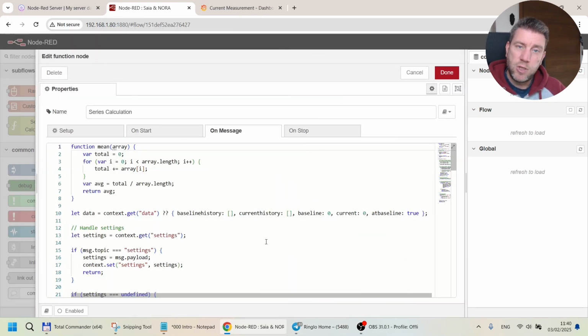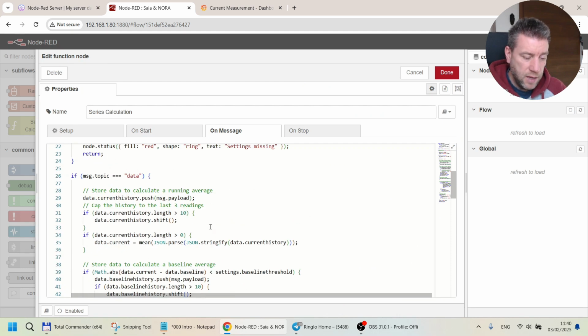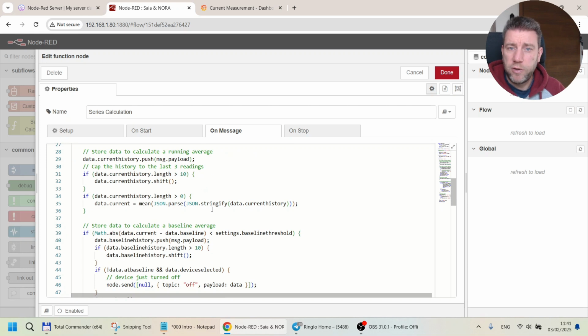So as I said for the dishwasher, because there is a slightly longer period in which it's not really doing anything, I had at least assumed that even when it's not doing anything, it still uses some current, which is, let's say, more than, I don't know, maybe like 100 milliamps, because I haven't really checked the specs, but I get readings for 2 decimal places. So let's say, 10 milliamps. If something uses less than 10 milliamps, it just shows 0. So probably the internal circuitry of the dishwasher uses less than 100 milliamps when it's just waiting in the cycle.